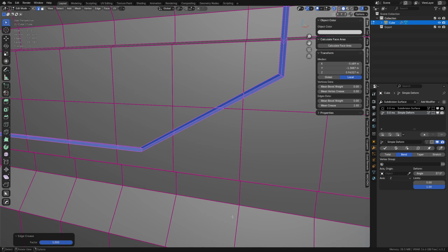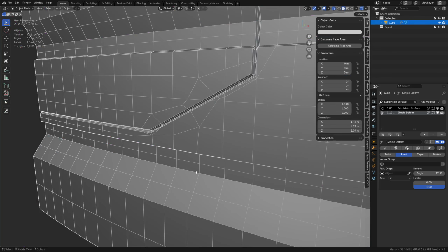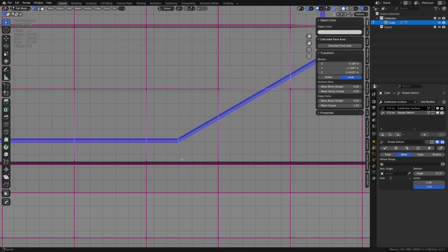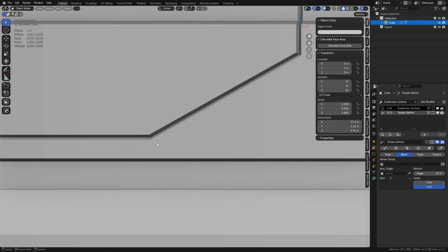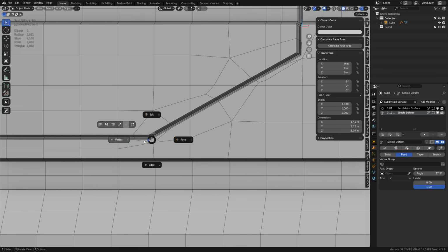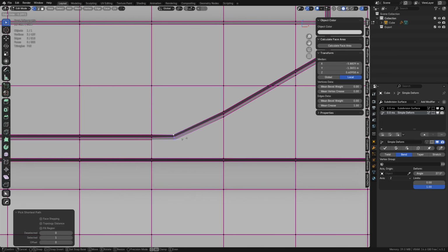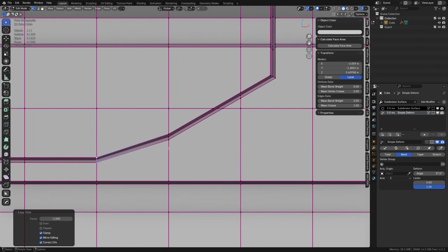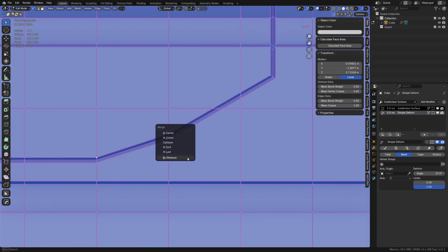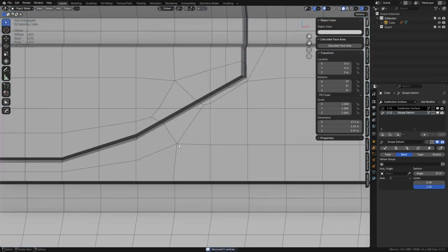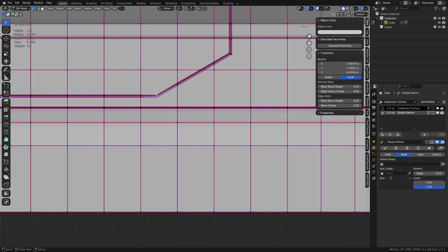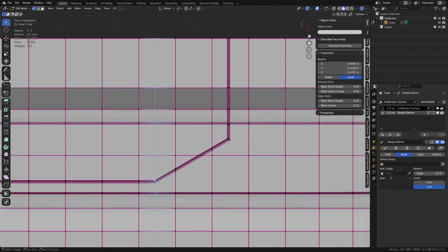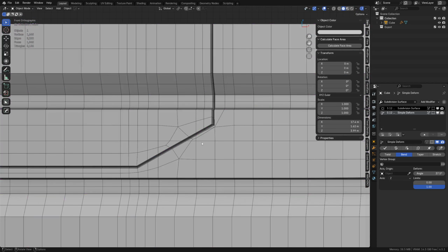But sometimes you can run holding edges on these, like you can bevel that outer edge, and sometimes that can be quite useful. You see this little edge here in the middle doesn't quite work maybe as well as we would want it to, right? We could use it maybe, but these usually work better, kind of hitting out to the ends of the edges like this for obvious reasons. It creates kind of a quad. So be careful with how you cut things too. Not that you can't use that, but you're probably going to end up running another edge out. And that's going to look better now when it subdivides.